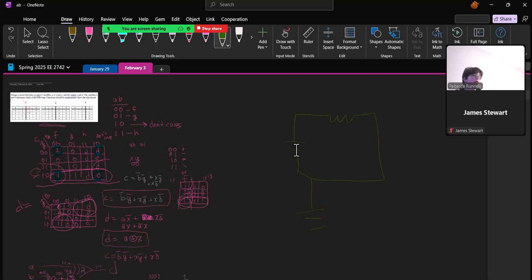And so the ground on the training kit is 0 volts relative to the 5 volts of the high voltage. So they're apart by 5 volts, the voltage difference. And that's what you need in order to drive the current. It won't work without that, because otherwise you'll have an open circuit. And if you have an open circuit, the current's not going to flow.